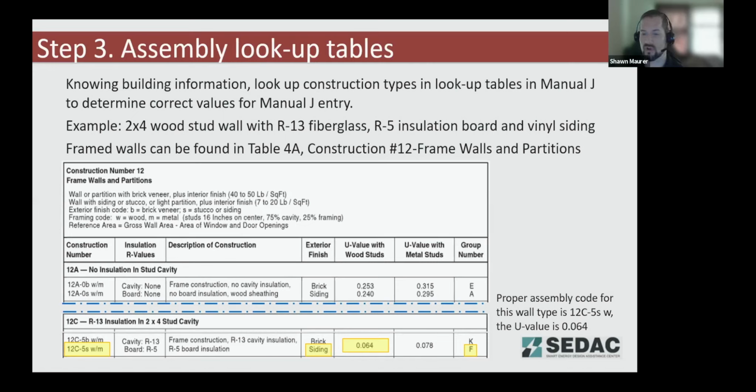And you also have to account for any overhangs that are shading those windows on the outside of the building. So even minor things like the bug screen are accounted for in this load calculation. It's important to be aware of those so they don't get accidentally left off.